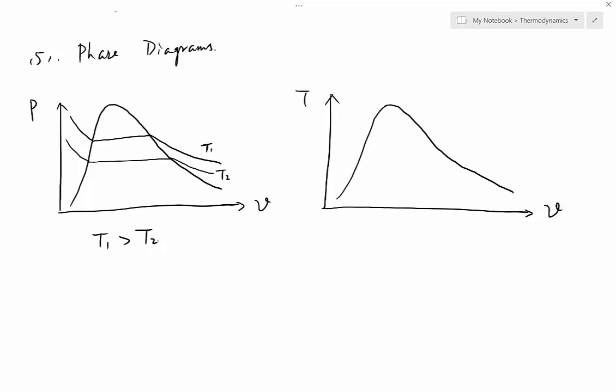Okay, and now let's move on to the T versus nu diagram. On a T versus nu diagram, we have something very similar. It's called a constant pressure line. How do you sketch this line? Very similar. Curve up this time. It's a curve up, and then a straight line, and then continue to curve up. This is a constant pressure line, meaning every point on this line has the same pressure. You can have multiple such lines.